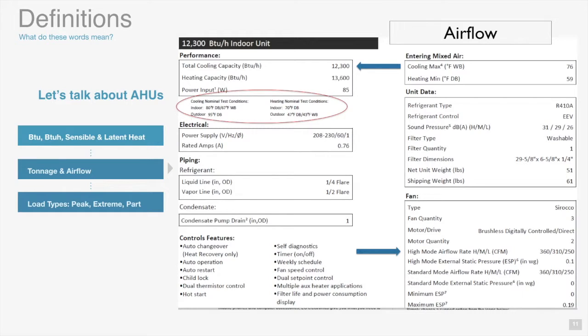And your outdoor temperatures may be different. Here in Austin, it's 100 degrees, so we would expect to get a little bit less air conditioning out of this unit than that 1 ton, just because the air that it's trying to exchange heat with outside during the summer is hotter than the 95 degrees that it was tested at.